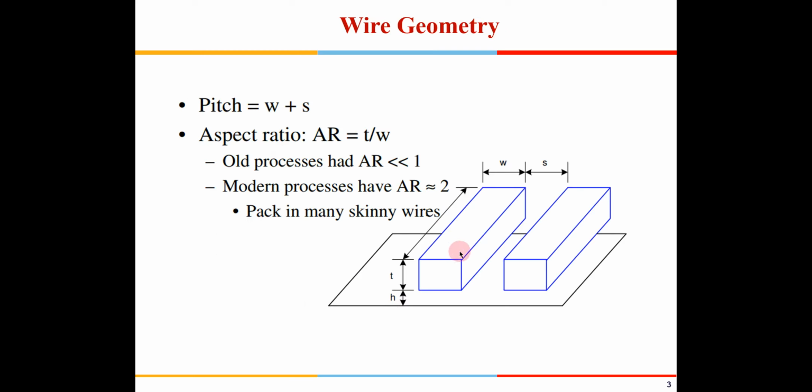Okay, so this is how a wire looks. There are certain definitions. This is the thickness of the wire, known as T. The small h is the insulator thickness between this and the next metal layer. This small h indicates the spacing between two layers, which is filled up with insulator, generally SiO2. W is the width, and L here is the length of the wire.